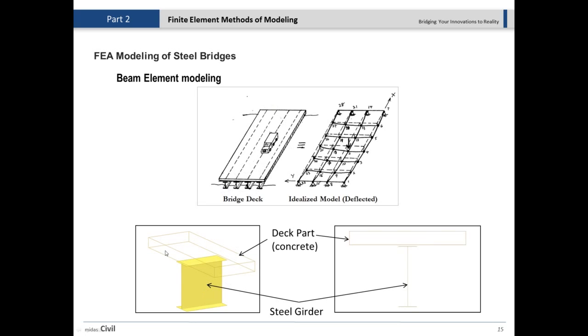One, we have to use a composite section to model the concrete topping to increase the stiffness of the girder, and also we have to use dummy transverse beams to make the girders work together. So by this model, we are satisfying the role of the deck, which is, one, making the connection between the girders to make them one system and work together. Another one is increasing the stiffness of the I-girder itself by making it composite.